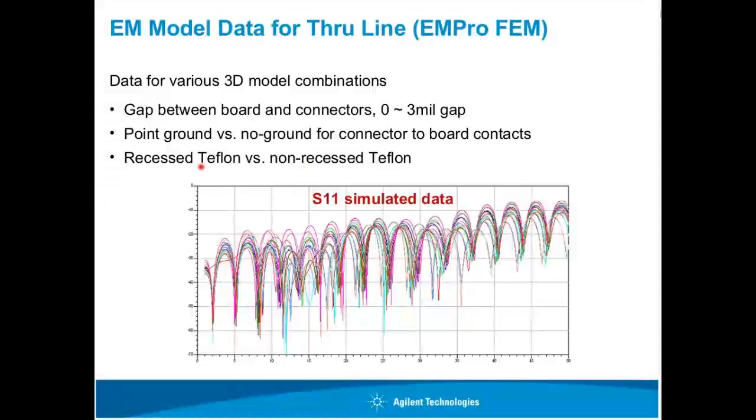By putting those variations into the design, we saw the results were quite varying from simulation to simulation, which is similar to the measured data we saw on the previous slide. So it will be very, very hard to just pick one of the measured data, which could be the best one, and try to match the simulation result to it. It will be a very, very hard task. So we need to understand those natural variations coming into the measured data as well as the simulation. We need to make sure the structures we are simulating, including those material properties, really represent the right values for the structure we measured.